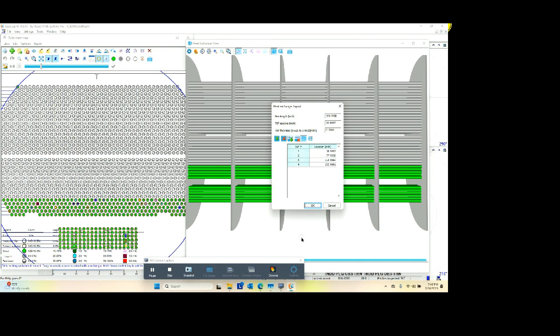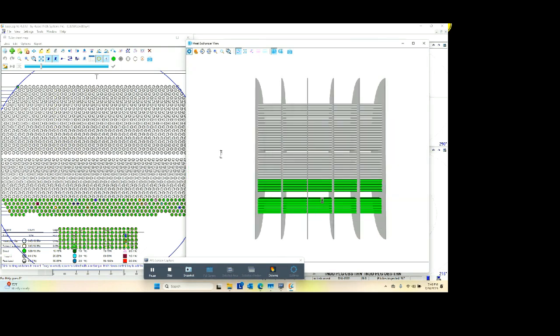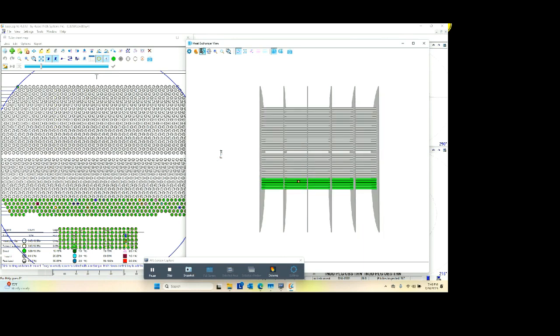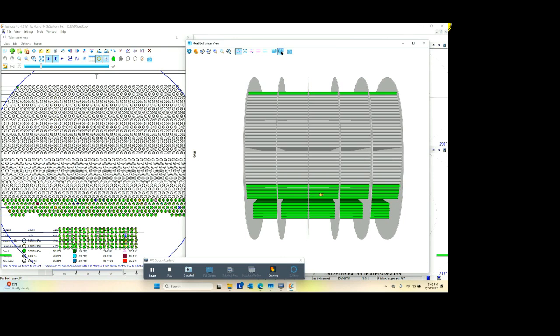each end. Okay, so now if you want to zoom through the tubes, you can hold down this button and you'll see little icons identifying where those local pits are located. This is the front tube sheet. This is the back tube sheet. We can actually reverse that view if you want to. So it'll do it from the back side instead of the front.